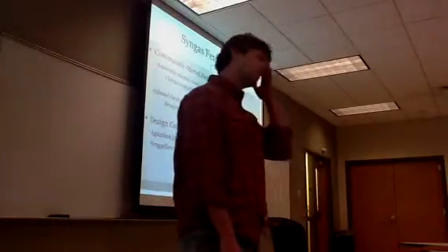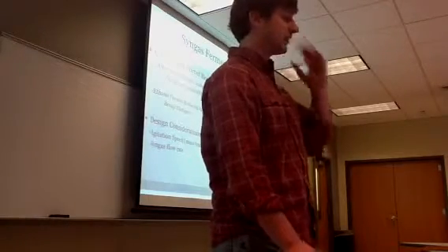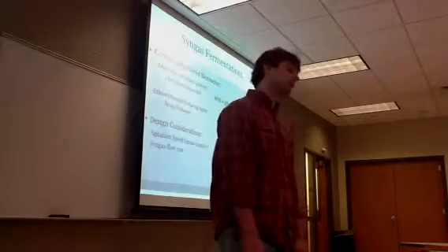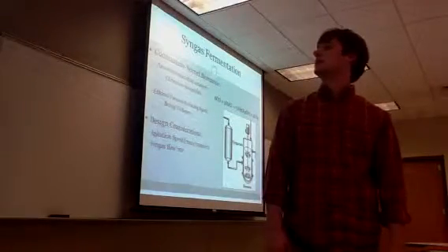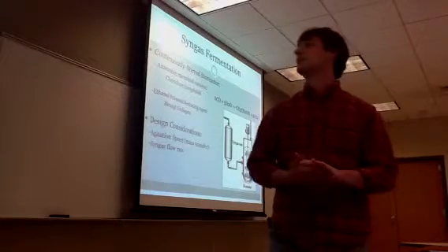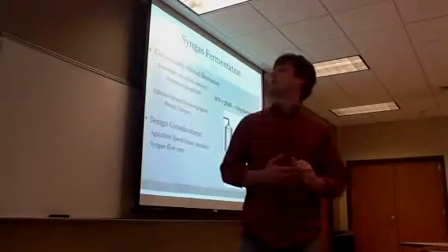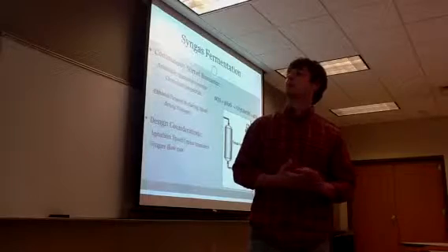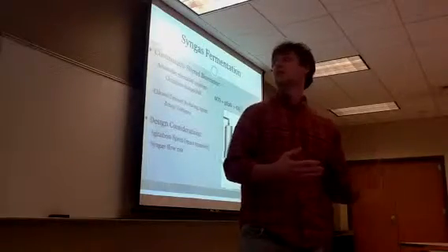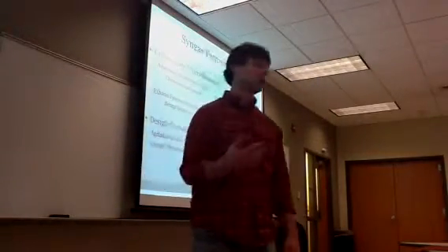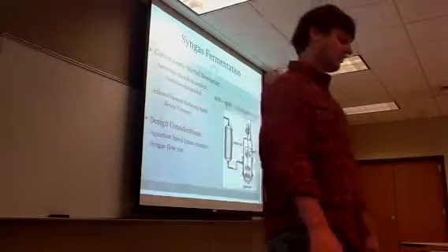Next stage is syngas fermentation. We'll be using a continuously stirred bioreactor here, with an anaerobic microbial catalyst in the acetogen group, Clostridium ljungdahlii. Broken down microbiologically, it will also be fed an ethanol-favoring reducing agent in the culture medium, about 30 parts per million of benzyl viologen. What this does is it increases the electron content, or the H plus content, and it favors the C1 carbon electrons that favor ethanol production.